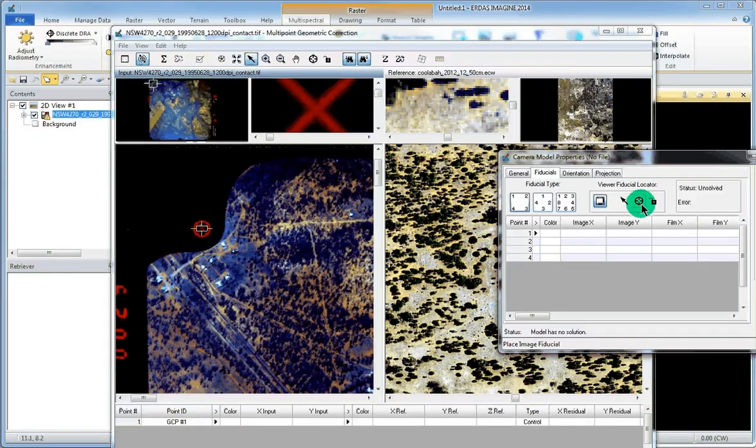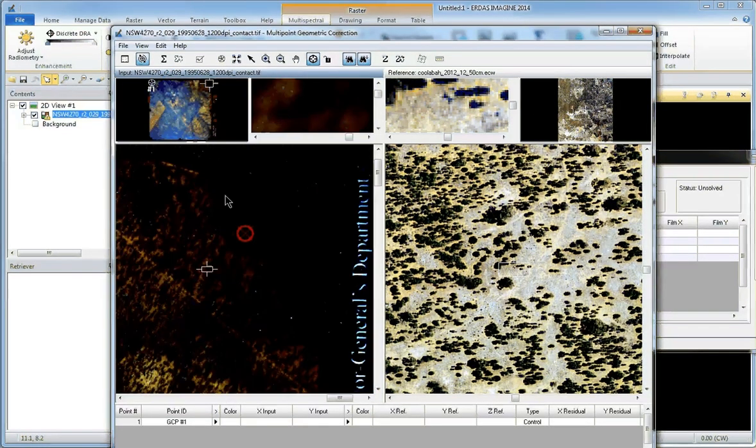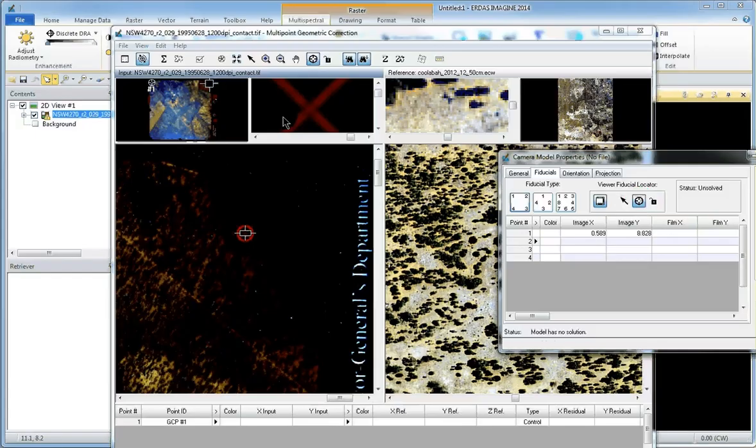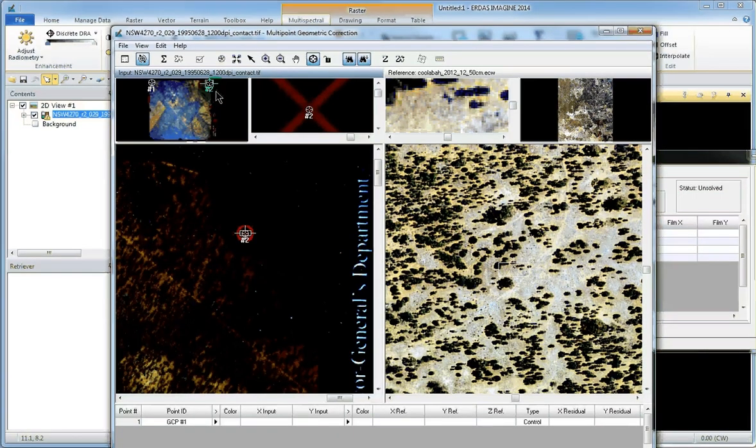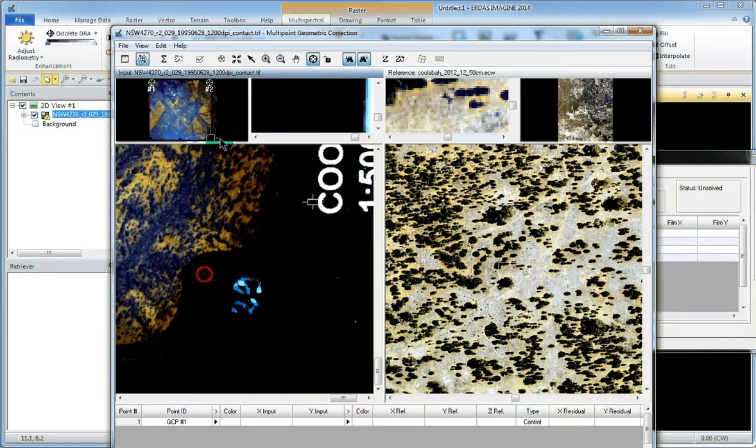Select the crosshair symbol, place the crosshair over the fiducial point and select it. Make sure that your arrow is selected, which it'll default to after you have placed the fiducial mark. If the tool is locked, you'll have to reselect the arrow. Drag it across to the next fiducial, highlight it in the magnifying box, again select your crosshair, drop the point. This will have defaulted back to the arrow key. Drag it down to the next fiducial point,